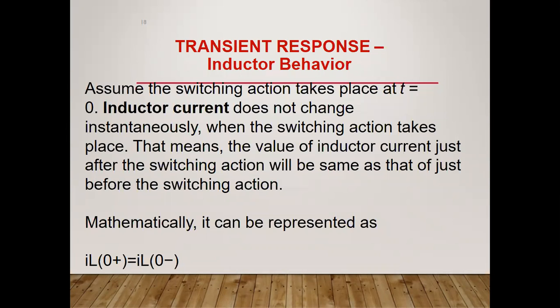So see here the transient response in the inductor, what change will we see here? If we assume the switch action takes place at a particular time, the time is nothing but zero. The inductor current, which is the current flowing through the inductor, IL, small i sub L, does not change instantaneously when the switch action takes place.